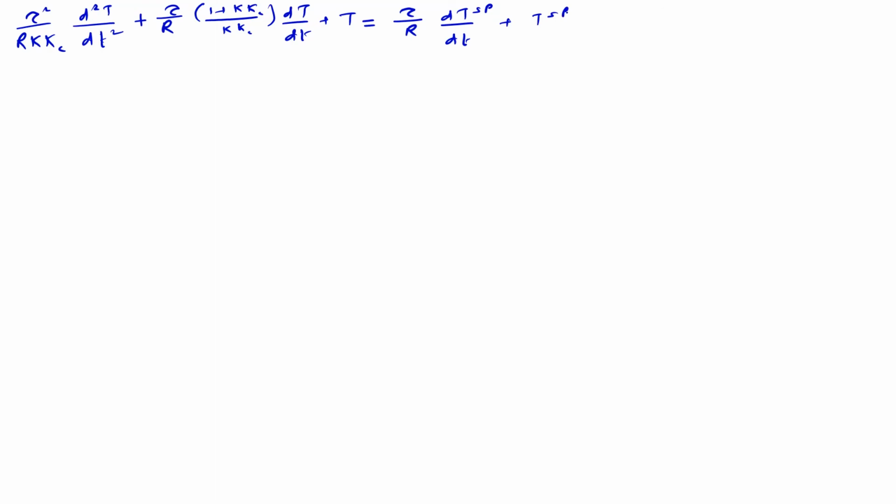So we know that for a unit step forcing, temperature varies as the temperature unit step. So temperature goes as 1 minus e to the power minus a t times b by square root a square plus b square times sine bt plus phi.